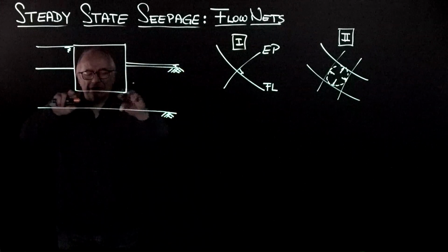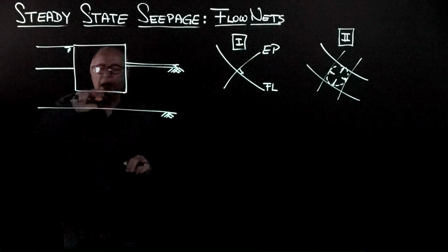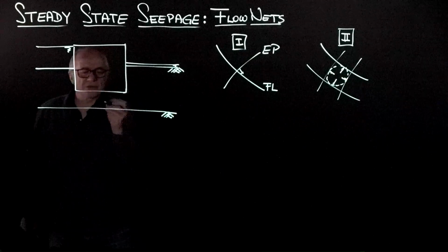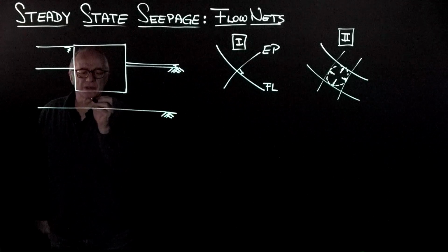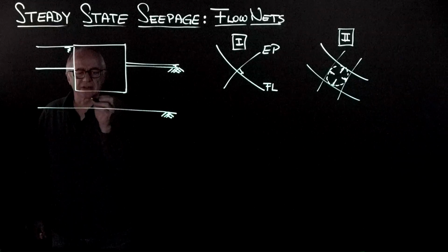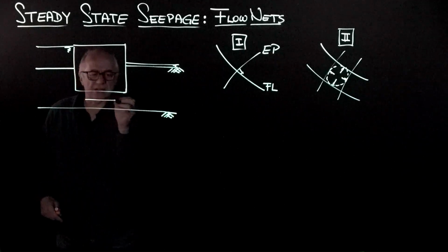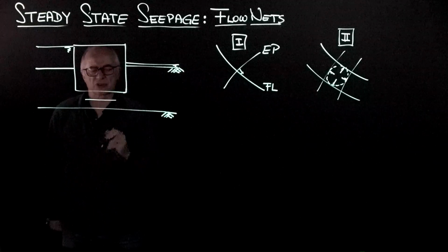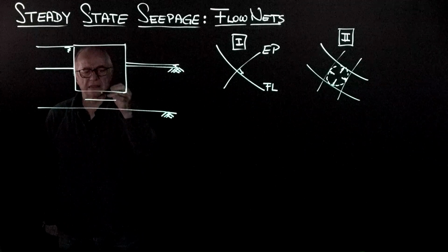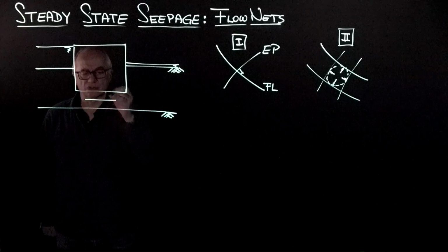This part of the flow net, where we have this flat surface, looks like a pipe. And so we can start doing a sketch here, and let's say that we're going to have only two channels, and far away from the boundaries, one flow line will be pretty much horizontal and equidistant, because these two channels are going to carry the same flow rate.